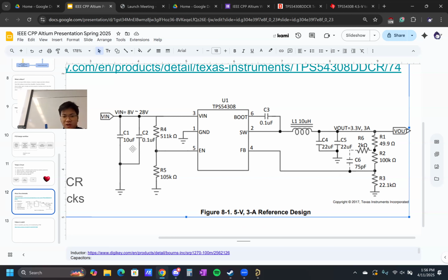If you're dealing with more high frequency noise, you're going to want smaller capacitance sizes, 0.1, 0.01. 0.01 really. 0.1 is still mid-range. For those of you who don't know about our 8-bit computer project, we're using 0.1 microfarad capacitors to decouple our chips.